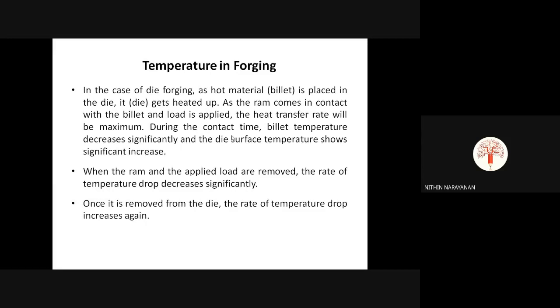As the ram comes in contact with the billet, then after that the ram is coming into contact with the billet and the load is applied, the heat transfer rate will be maximum. So at that time, when the load is applied, plastic deformation is happening and the heat transfer rate is maximum. So the die, the billet and the ram are all in contact. During the contact time, billet temperature decreases significantly and the die surface temperature shows significant increase.